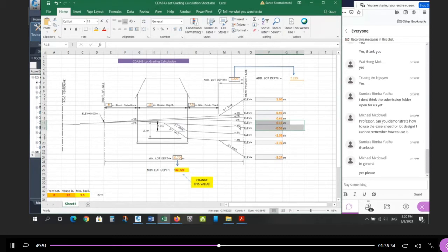So you might have to do this twice. The command is high-low, 2% up from the front, 2% up from the back. If you get a solution inside the building envelope, you're done. If that doesn't work, try 2 at the front and 3 at the back.